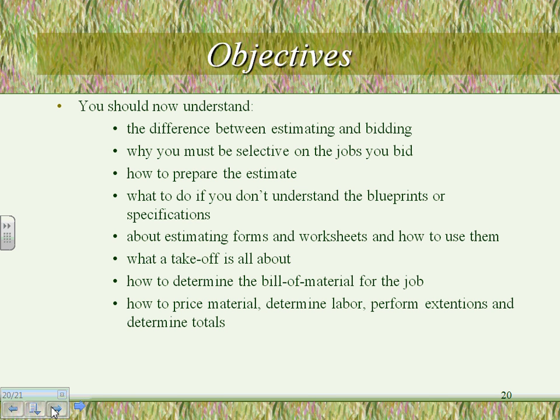Okay, if you guys go to page 58, please. On page 58, they have a bunch of details. Those of you who have never wired and want to be estimators or project managers, these are really good to look at. Look at detail number 1, guys, fluorescent lay-in fixture. It shows you that there's a 4x4 box, and there's a fixture whip tied to the actual installation, tied to the fixture. So you have to account for the fixture whip.